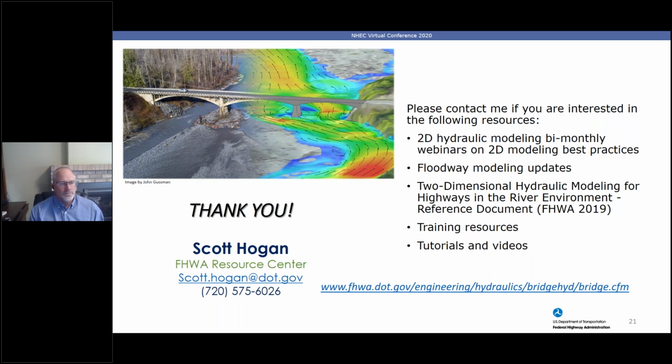Isn't the flow direction dependent on the break lines in the topography and the definition of the mesh? Well, yes, the flow direction is directly computed within the 2D model. And so that's what's nice about using the base flood elevation contour lines, is that at every location, they are perpendicular to the flow because it's delineating that even water surface.